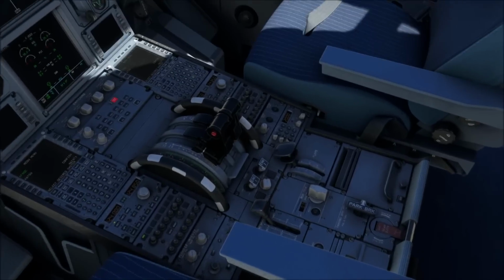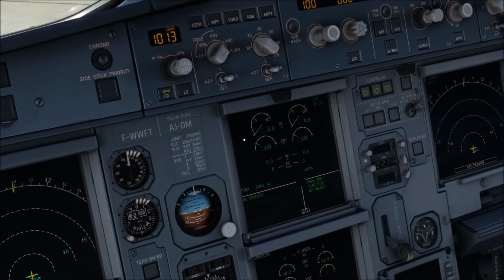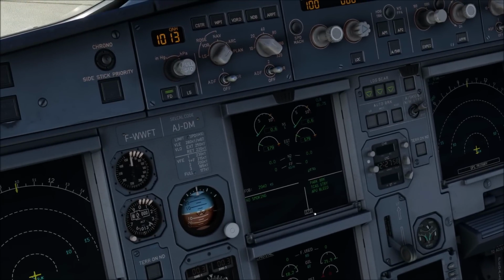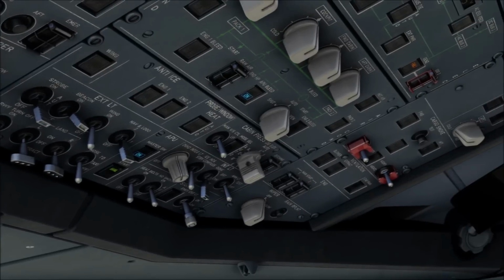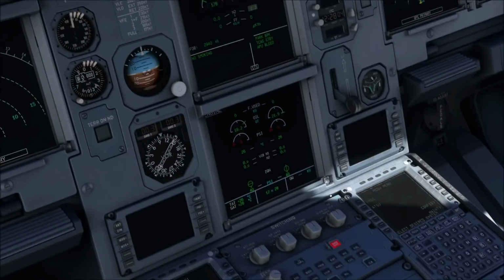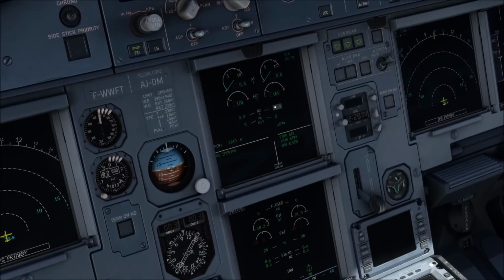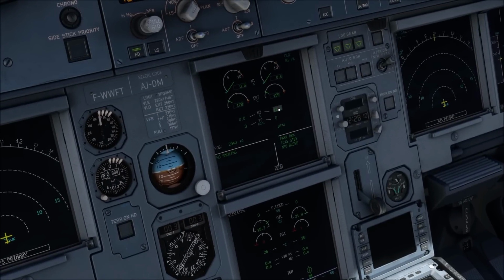Thrust lever idle, engine mode selector normal, then ignition start. Okay, our parameters are all showing in green. So, engine manual start push button on. We'll start engine number 2, on. Start valve, check in line, N2 increases, oil pressure increases.